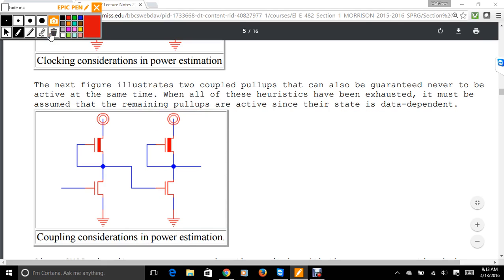And when you get into these concepts of PVT corners, you really have to worry about whether or not your circuit is consuming too much power in specific areas, because if you're constantly using one part of your device but you're never using the other part, then over time, like with your laptop, you have to make sure that your energy use is distributed properly. Otherwise, you're going to get burnout, but you have all the rest of the CMOS that's hardly been used. So that becomes a challenge.